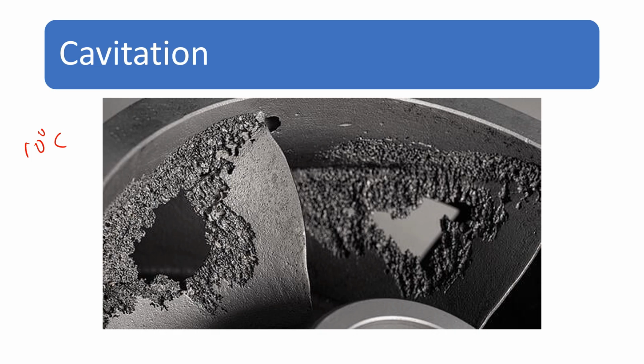So you can see that because of cavitation, the impellers are getting damaged. Here the water is boiling at 10 degrees Celsius because of the pressure reduction, because the pressure here gets dropped to 1.23 kilopascal,